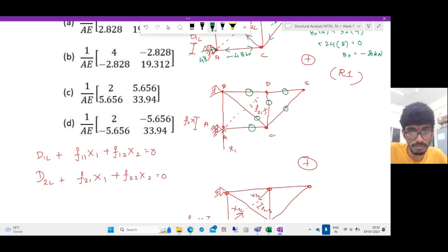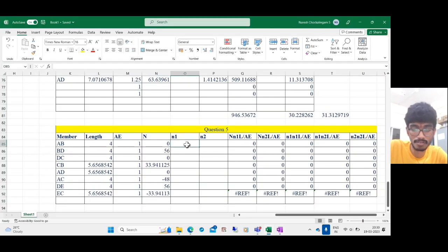If you apply a unit vertical force 1, this will be subjected to a compression of -1, and there will be a downward reaction. Except the member AB, which has a force of -1, all others are 0.